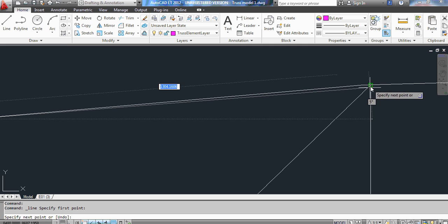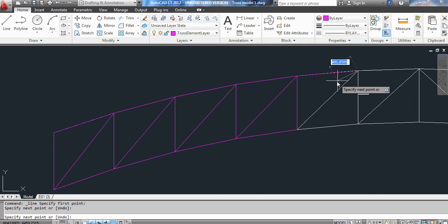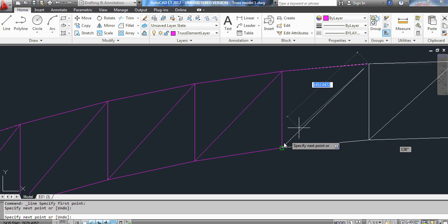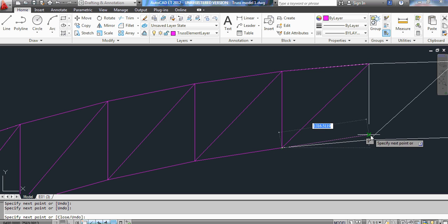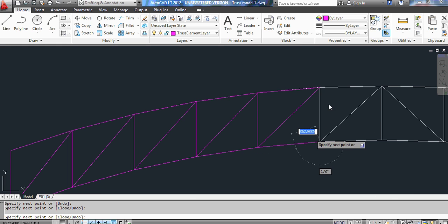So patiently trace the trusses, and let me also repeat this because it is very important: don't assume that the trusses you are seeing can just be read off directly, because the person that did the truss might not have been careful enough to ensure that the lines connect at the joints.